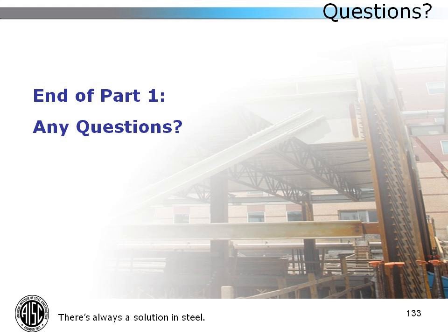Absolutely. That is using the bearing mechanism that we just discussed, and that's basically instead of using embedded plates like what we were showing there, you're using the angles as an embedded plate. So yes, certainly. You're allowed to use, I believe, 1.7 f'c as your bearing strength, which recognizes the increased confinement of the concrete. And I believe the question goes on to ask what the maximum and minimum spacing between the angles would be. If you look in the specification provisions, the detailing provisions for the steel anchors, I would follow a similar provision for steel anchors in composite components with a maximum of about 24 inches between angles.